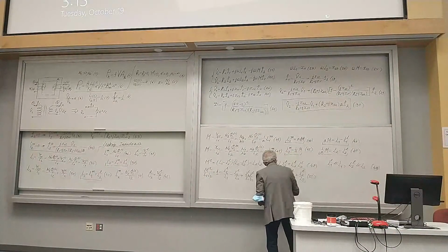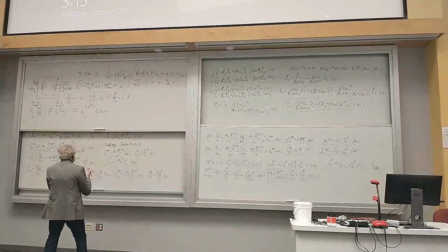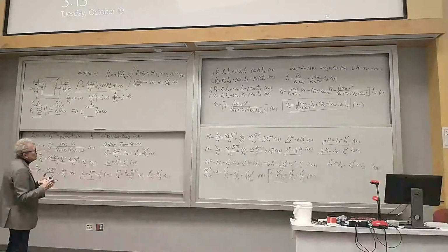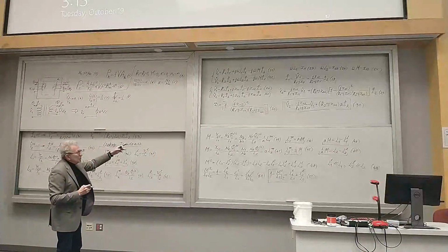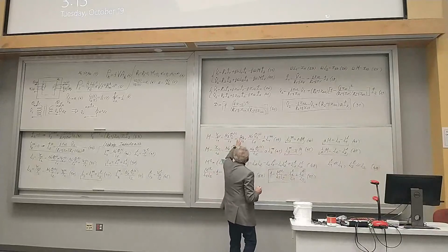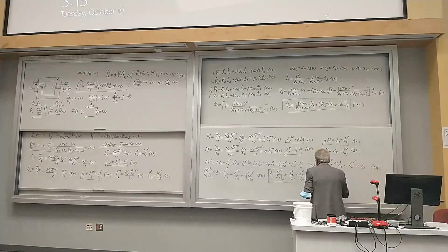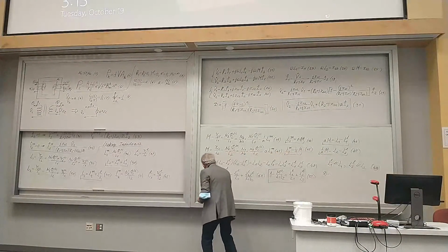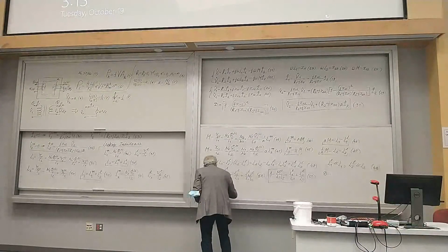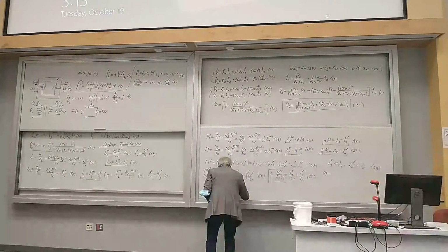I'm almost there. Then I will go to the expression for D, which determines the property of the transformer. You can ask, Professor, what does it have to do with D? And where is my expression for D? My expression for D is formula 30. In formula 30, as you can see, resistances are very small in comparison with reactances. So R sub 1 is very small in comparison with the primary reactance, and R sub 2 is very small in comparison with the secondary reactance.